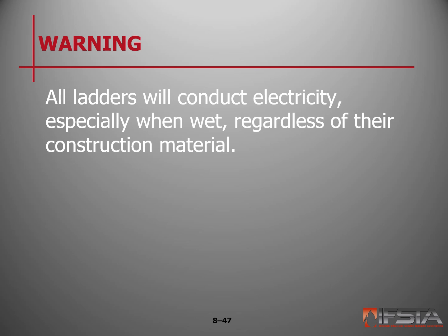Again, all ladders will conduct electricity, especially when wet, regardless of what they're made out of. Even wooden ladders conduct electricity. So again, look up, check for overhead obstructions, power drops, and other energy source type equipment.